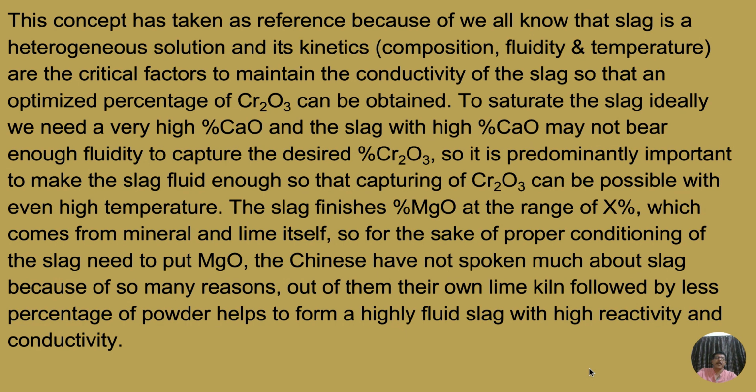So it is predominantly important to make the slag fluid enough so that capturing of Cr2O3 can be possible even at high temperature. The slag finishes with a percentage of MgO in the range of X, which comes from the mineral and the lime itself. So for the sake of proper conditioning of the slag, we need to add MgO.